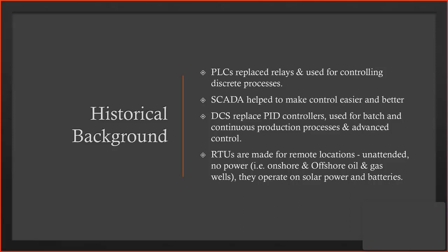By harsh, I don't mean stones dropping on these RTUs, but there could be high temperature, very low temperature, or high pressure, factors in which normal PLCs would not sustain. They would break down, melt down, and stop functioning.